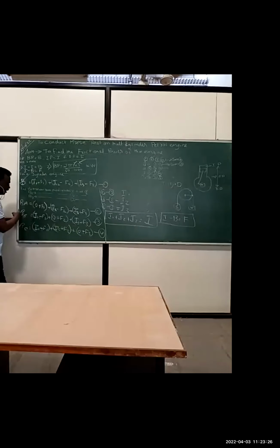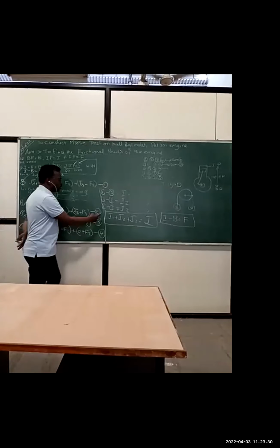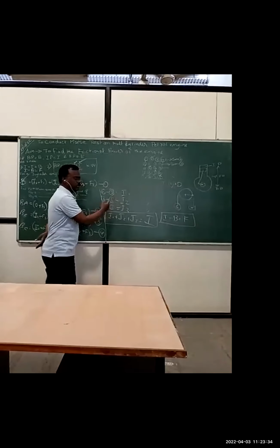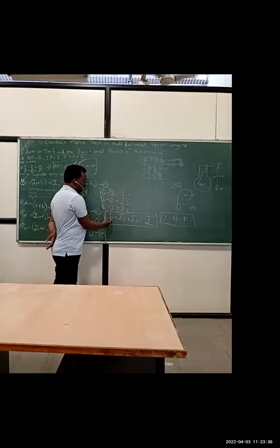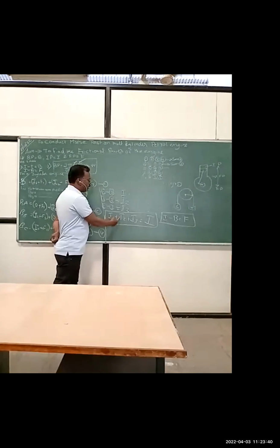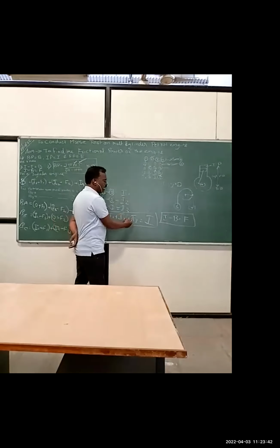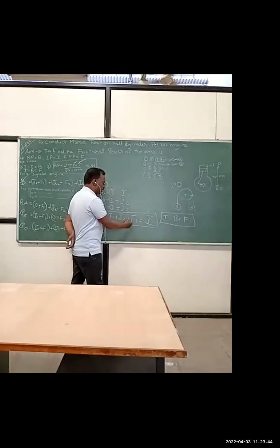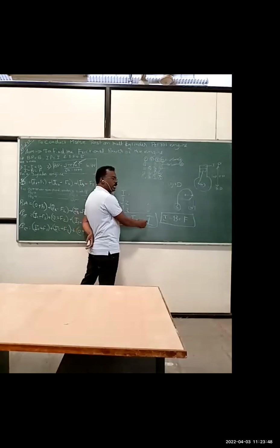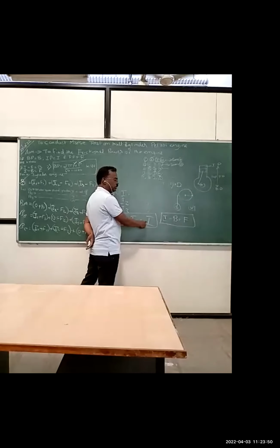So you have cut alternatively cylinder number 1, 2 and 3, and whatever you are getting is I1, I2 and I3. Now what is I1? I1 is the indicated power in cylinder number 1. I2 is the indicated power of cylinder number 2. I3 is the indicated power in cylinder number 3. So what will be the total I1 plus I2 plus I3? The indicated power of the complete engine.